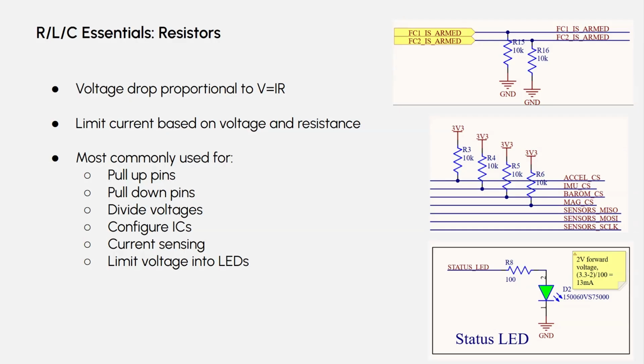But as soon as you have an active device getting on that bus, let's say your microcontroller, think Arduino or Raspberry Pi, if it decides to drive that pin high from a state of not doing anything, the resistor is not strong enough to stop it from driving it high.